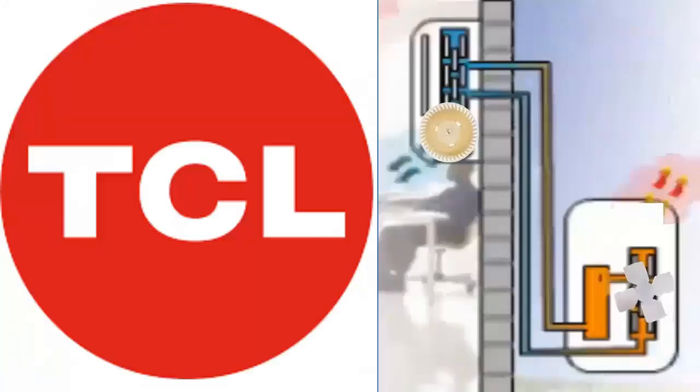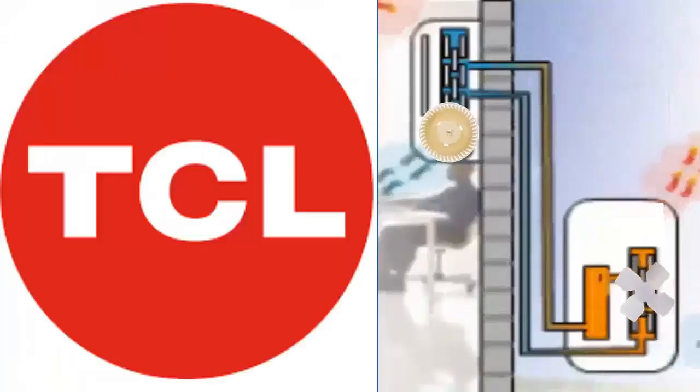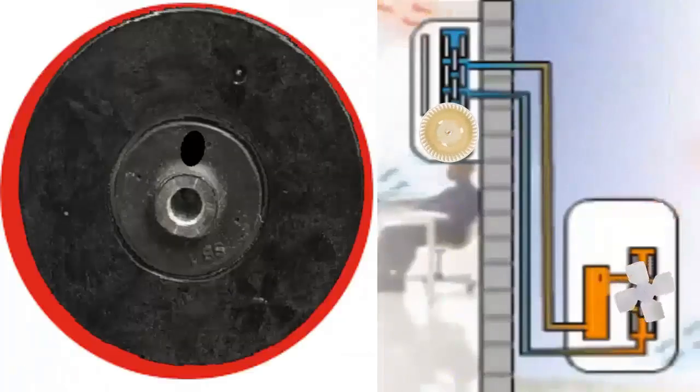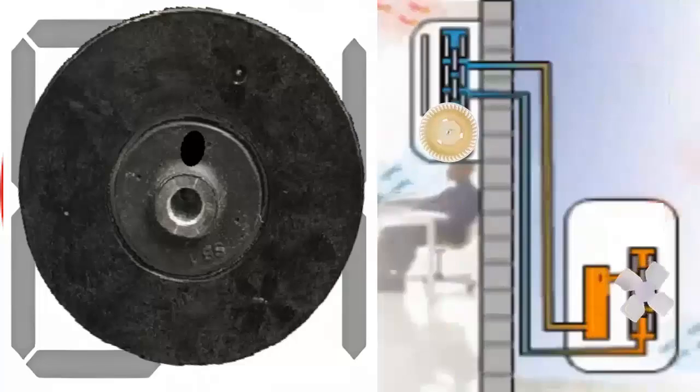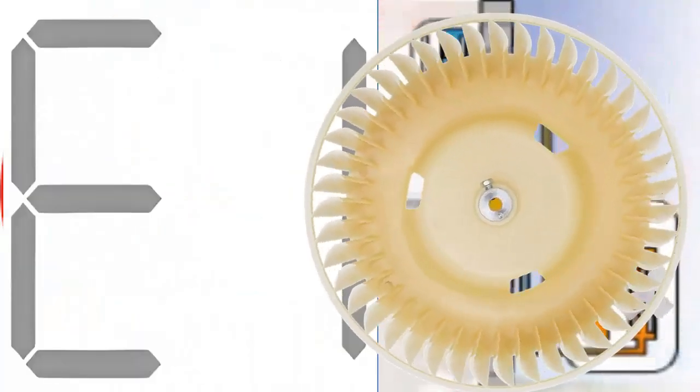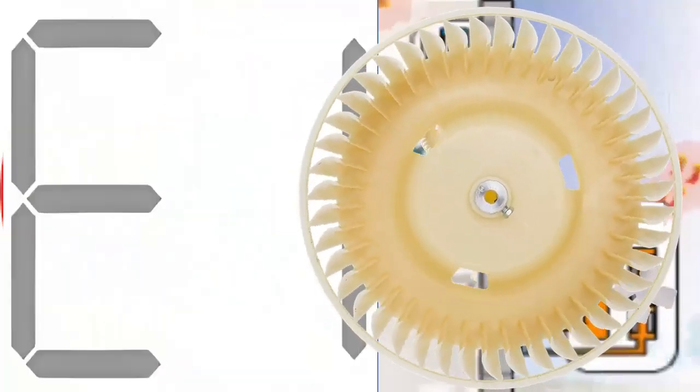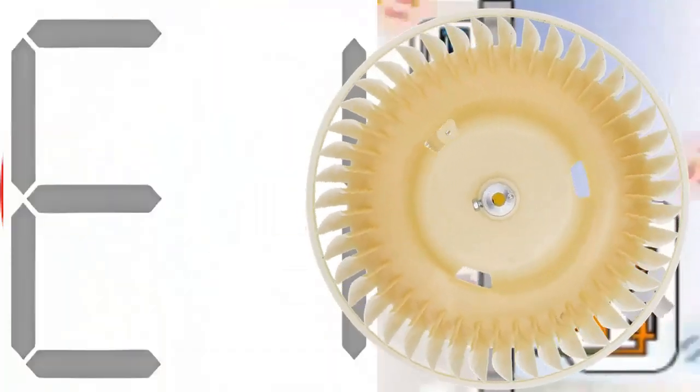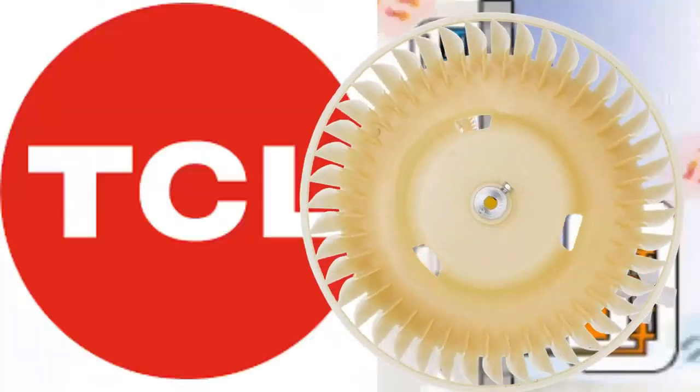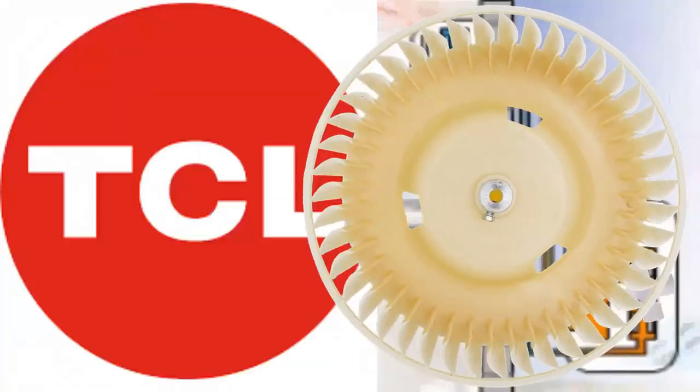4. Check the cleanliness of the turbine air filter of the indoor unit, so that the equipment is in optimal condition. Remember to visually verify the correct rotation of the fan. With the equipment turned off, verify that the rotation of the fan turbine is completely free to rule out mechanical problems in the fan.